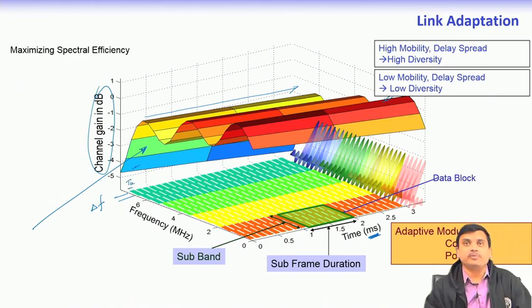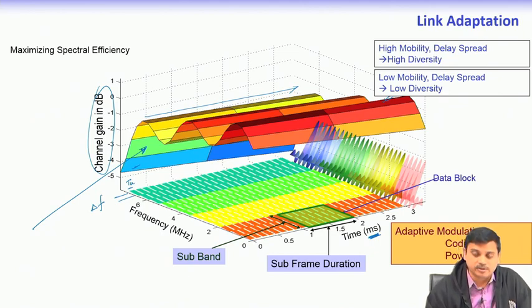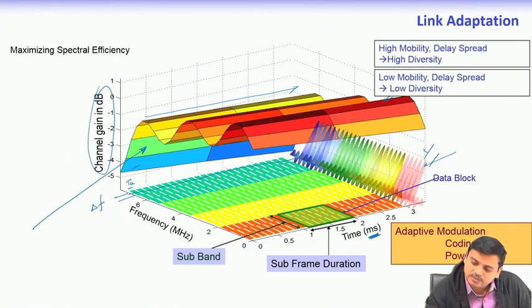So, this is for representation purpose that we have drawn this particular picture. So, these are reflecting the subcarriers, so that you can clearly see that if you proceed along this line, it is one of the subcarriers, and any one of the subcarriers has a spacing of delta f, okay, and each of them are TU durations. Okay.